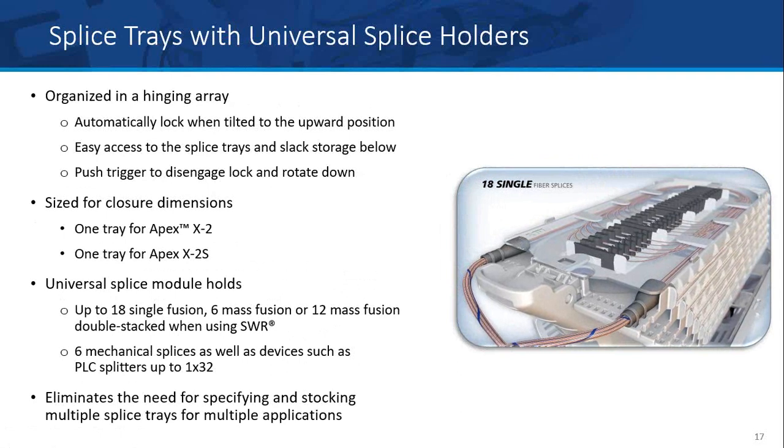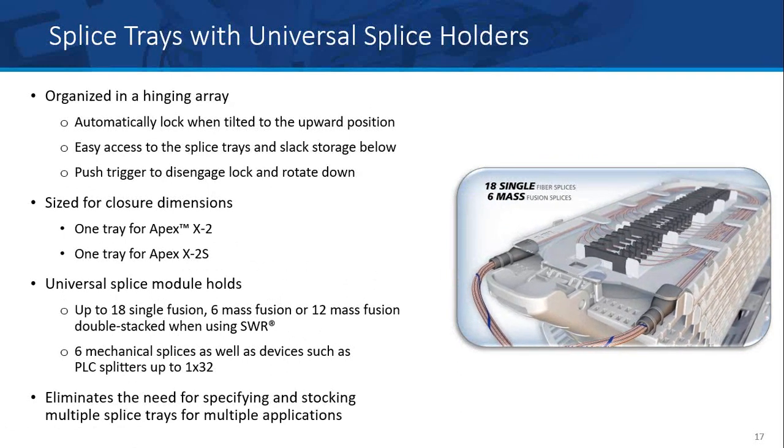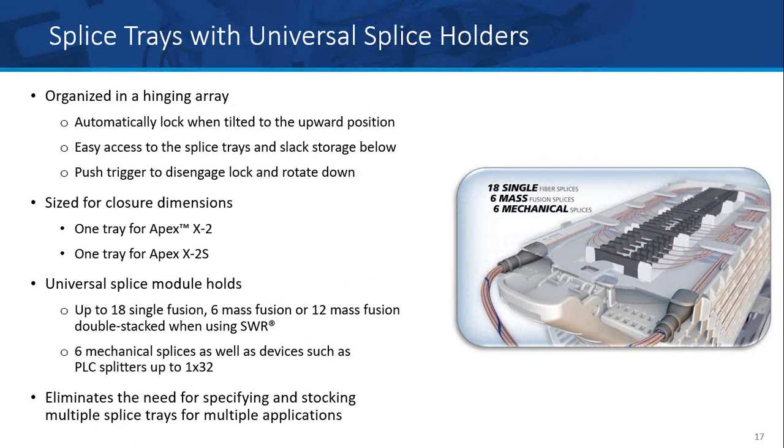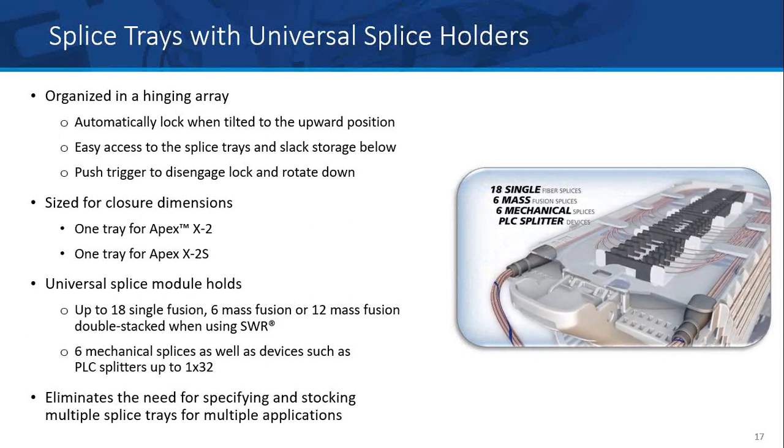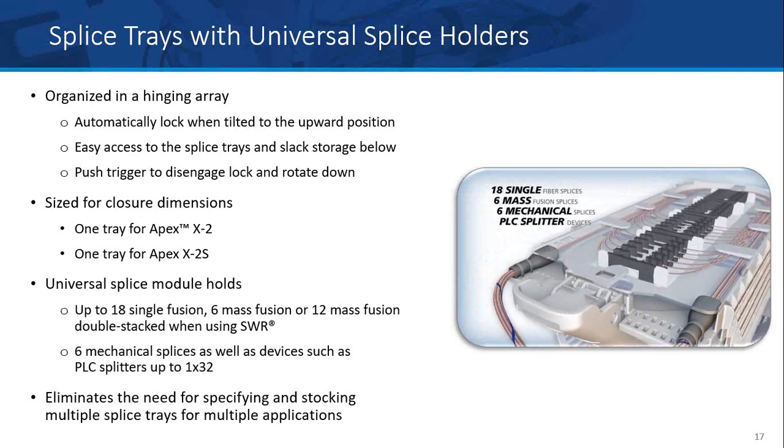All right, so as far as splice trays, so with the wrapping tube cable, spiderweb ribbon, another advantage of it is those ribbons separate very easily. So if I utilize a spiderweb ribbon technology inside of a fiber to home network, and I want all the advantages of the mass fusion splicing, but occasionally I need to drop off 12 fibers or even 1 fiber, say I'm splicing on a drop or I'm splicing on a multi-port terminal or something like that. Then you could potentially have mass fusion and single fusion all occurring in the same closure.